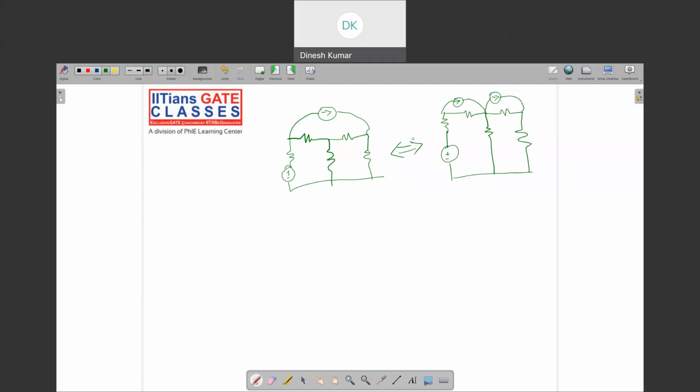Okay. So these two are electrically equivalent because if you check this node, this is the extra node we have added, right? So some current is actually coming and the same amount of current is actually going from here, right? That means this nodal equation will be automatically satisfied. So this type of equations are very important, like when we write the nodal equations, we can directly write a node equation in this one. Similarly, if this is something like a voltage also, we can write in this particular form.